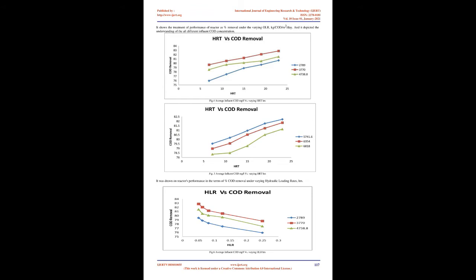The addition of nutrients was not deemed necessary since the wastewater characteristics indicated an adequate concentration of the essential proteins and trace elements. No dilution or recycling feed was made in the beginning or at any of the study phases. Chemical analyses such as pH, BOD, TSS, VSS, TDS, and COD, to determine the wastewater quality parameters, were conducted according to standard methods, APHA, 2005.